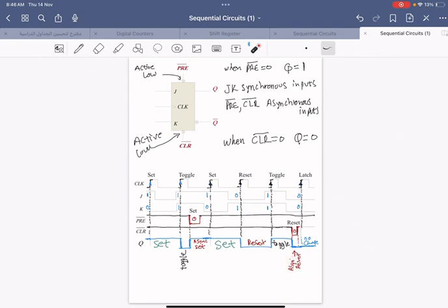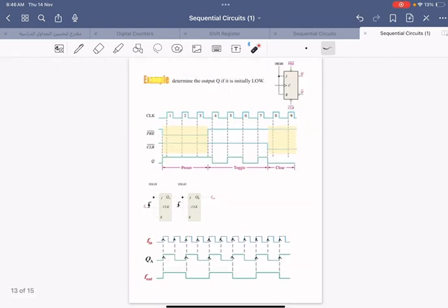It's a reset. We call it a synchronous reset. But because it's going back again here, the clock will wait. This is the waiting time here. Before the clock, nothing will happen. It will stay reset till there is a 0 and 0, which is no change, and then there is no change here. This is how the waveforms are working for this one.